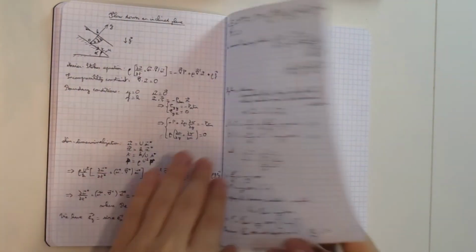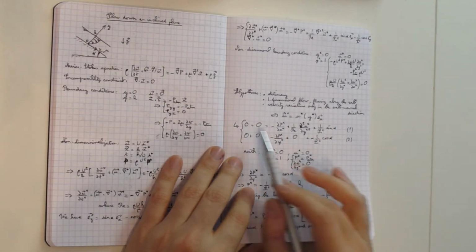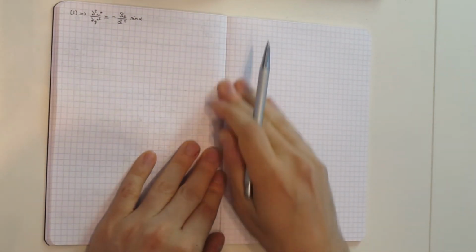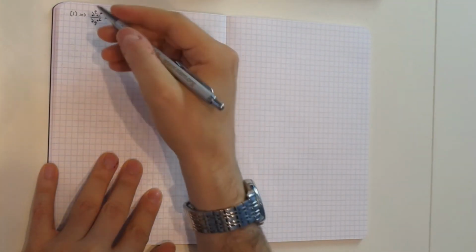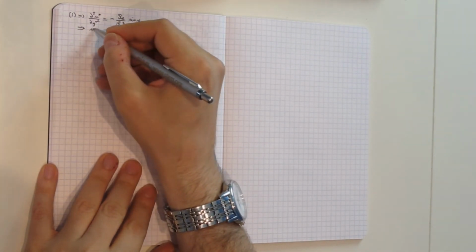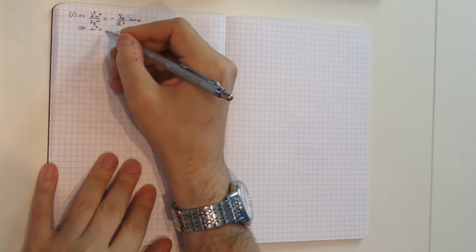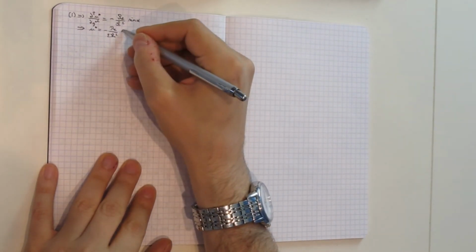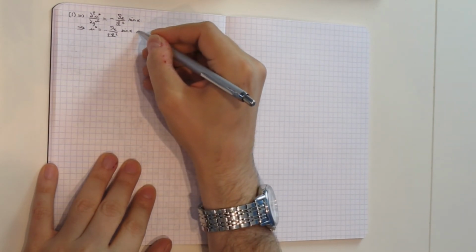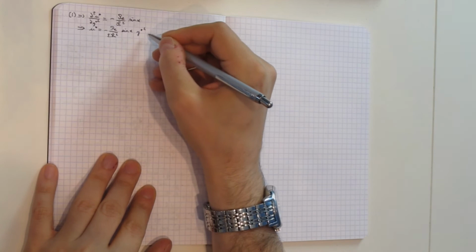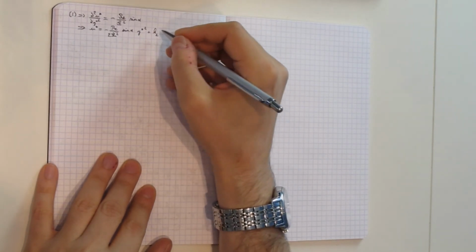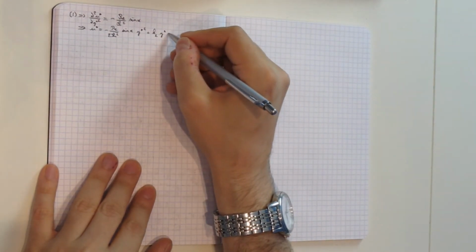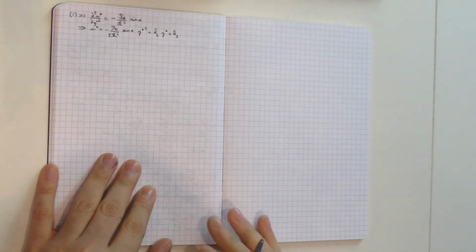Okay, so what I have done here is send this to the left hand side and multiplied by the Reynolds number, adding a minus sign in front. And so this equation solves pretty easily. So that gives us that u star is equal to minus the Reynolds number over twice the Froude number squared times sine alpha times y star squared plus a second constant of integration. We had a first one already when we solved for the pressure, times y star plus K3.